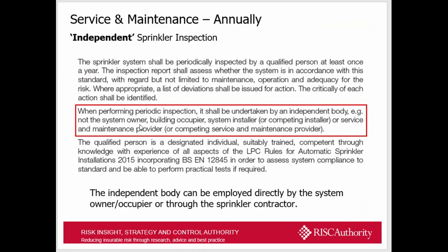From this as well, there is an independent inspection requirement, and this is not undertaken by the sprinkler contractor. It's an inspection on the system technically against standard. So this is done by an independent person who's qualified. It should be done on an annual basis, and it shall report whether the system is in accordance with the standard. So it could be to BS EN 12845, or it could be an LPC sprinkler system. So the report will be against one of those standards, and a report is written.